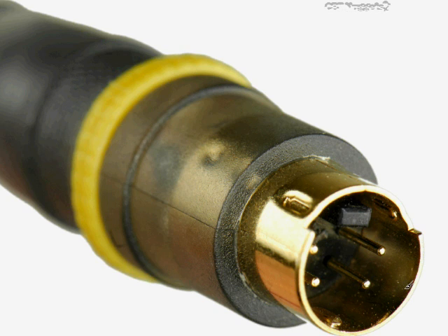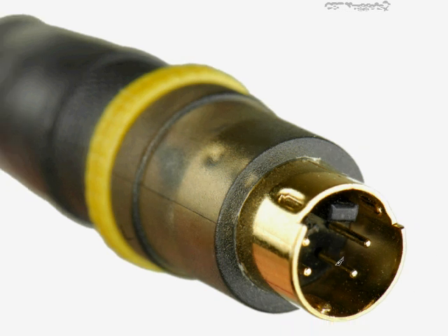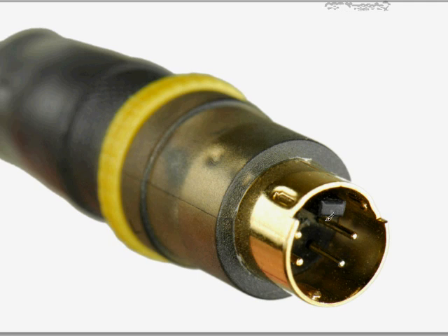Again, it's easy at first to confuse this with something like a keyboard or a mouse connector, because they look very similar, but they are a little bit different, and they do have different indentations in them. For example, this key right here in the middle is going to be different on a keyboard because it appears vertically instead of horizontally, and there's a different number of pins. The S-video connector has 4 pins, whereas the keyboard or mouse connector will have 6.